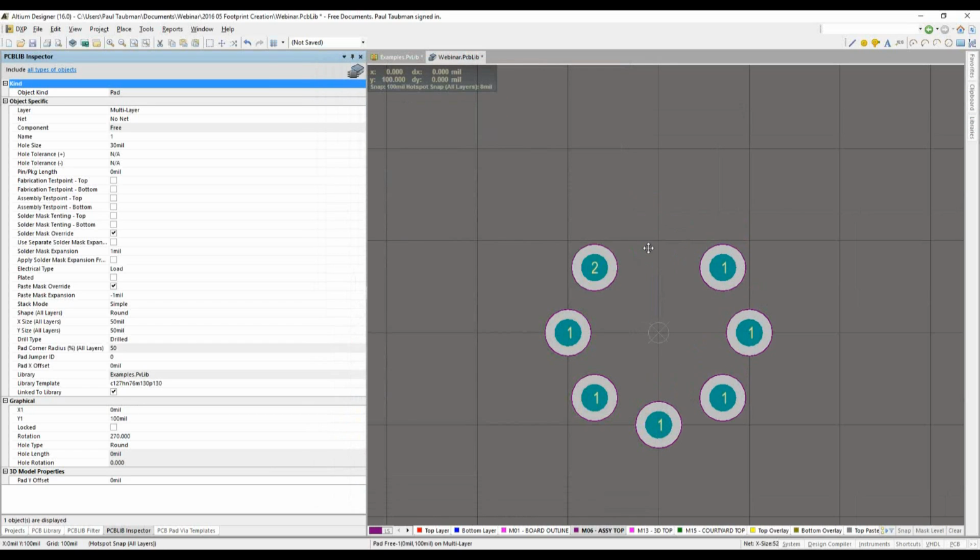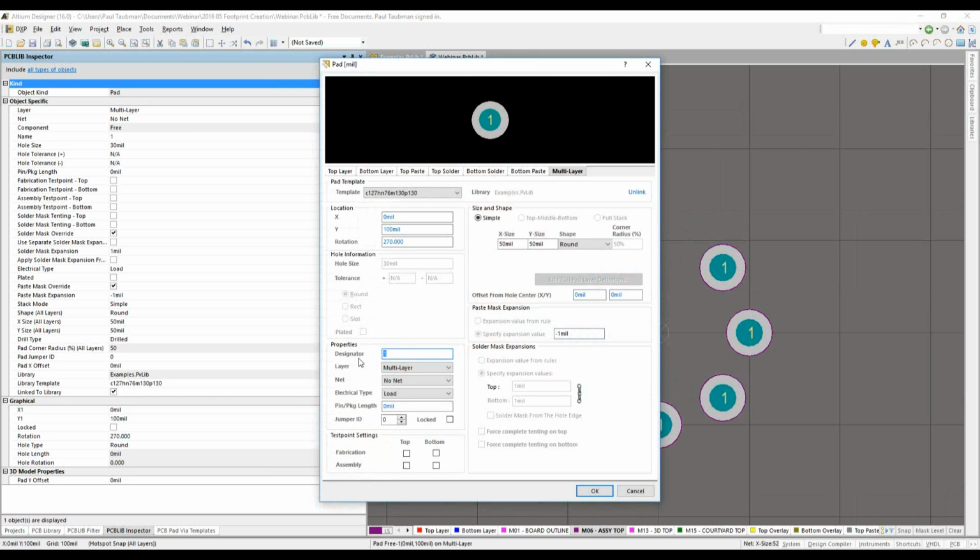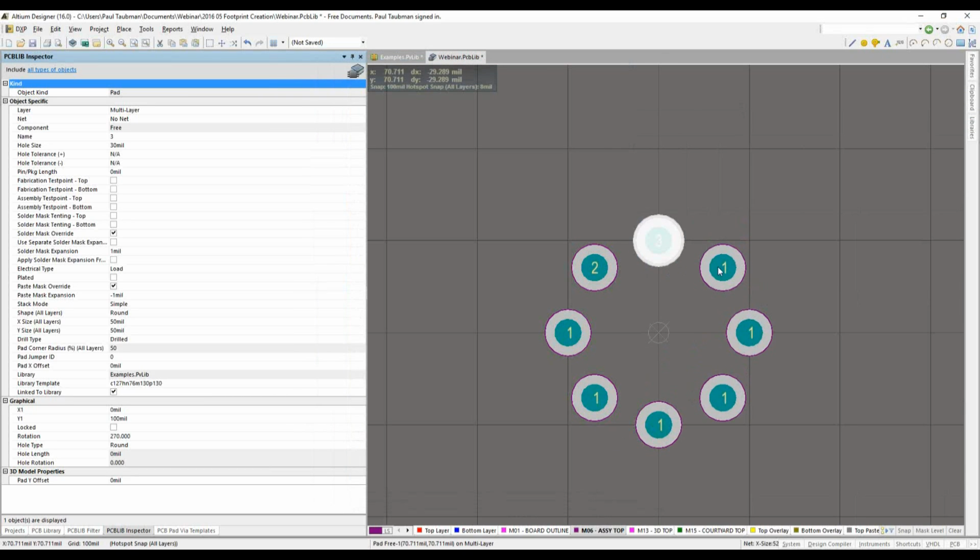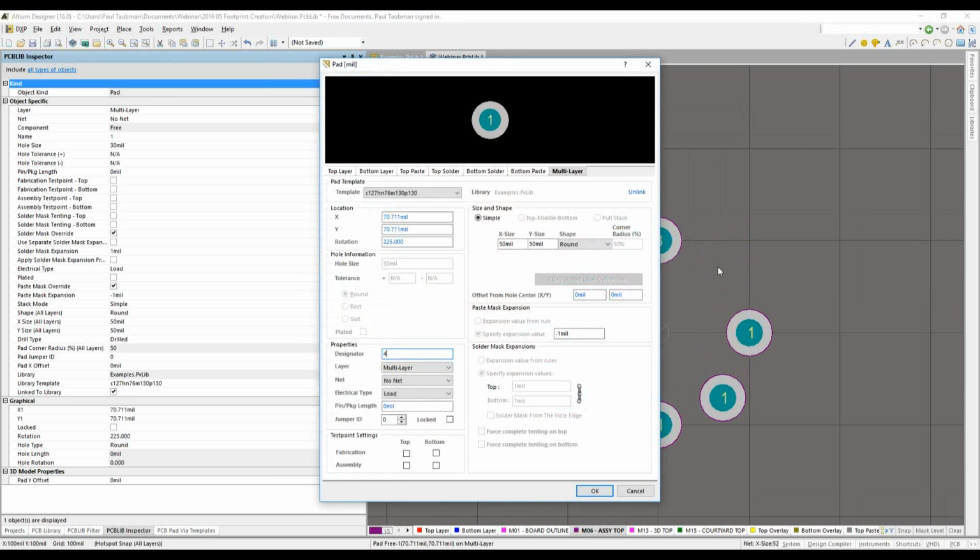How is that? Well, I have to double click into to get into its properties. But notice that the designator is already the active tab or the active region. So really what I just need to do is I can hit the 3 key. And more so, if you look at OK and cancel, these are actually associated with the OK being with the return or the enter key, and the cancel is actually with the escape key. So I can just hit 3 return and not do anything else in it. So if I double click into this, I can do 4 return.